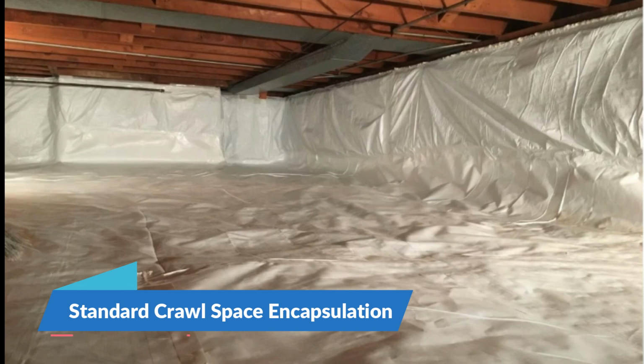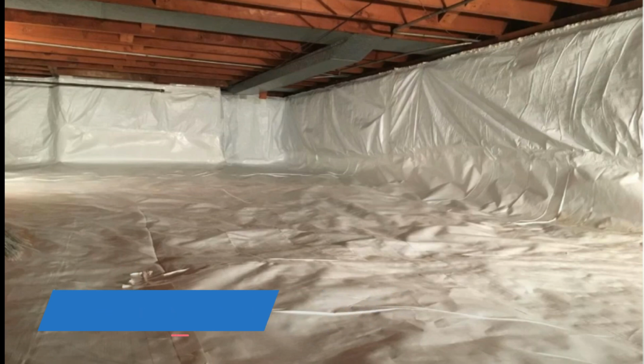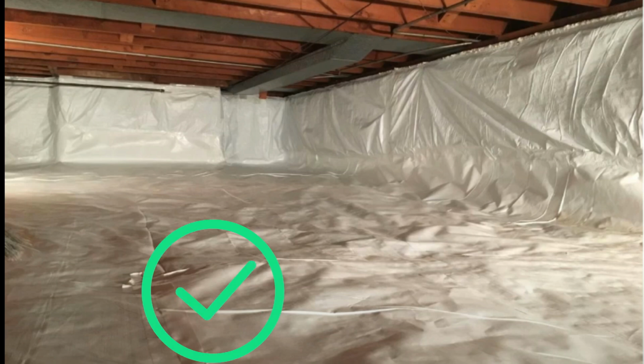In reality, taking into account the fact that the crawl space floor is never perfectly level, and the fact that you can only stretch the vapor barrier so much, this is a solid encapsulation. With this crawl space encapsulation, we have a good vapor barrier on the floor and the walls. The issues related to air infiltration have been addressed not just from the outside into the crawl space, but also from the crawl space into the living space.